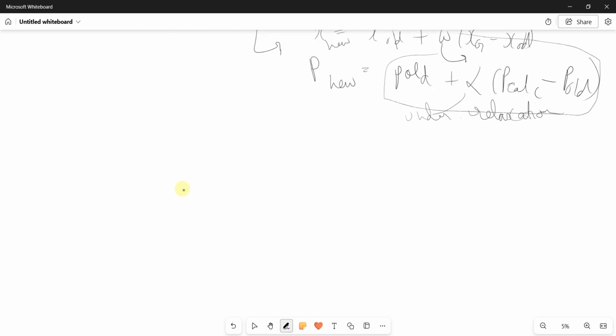Now the next cause could be poor initialization. You always initialize the values for the parameters, right? So that you can start. That is exactly where you're starting your guesses from, so that you can run the simple solvers, or whichever solvers you are going with.